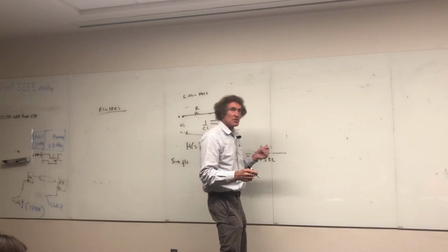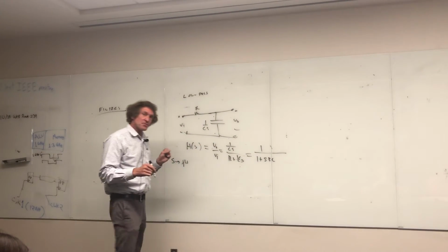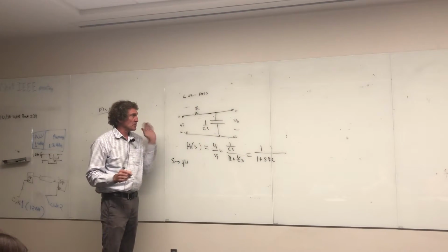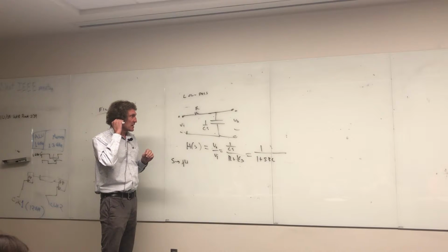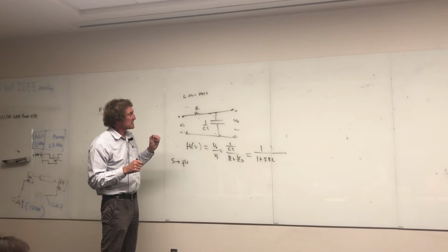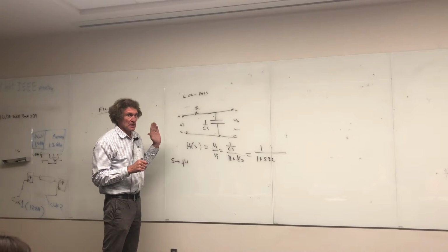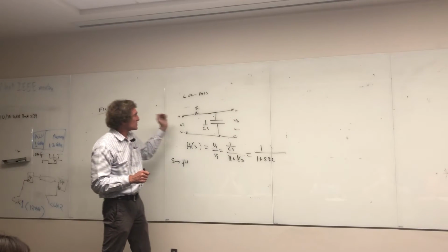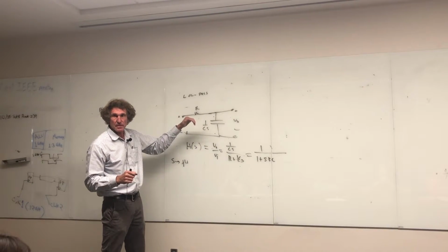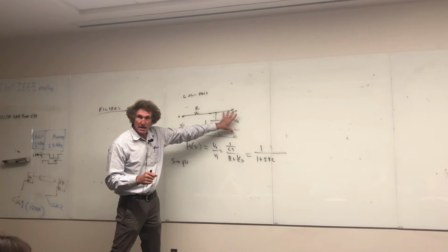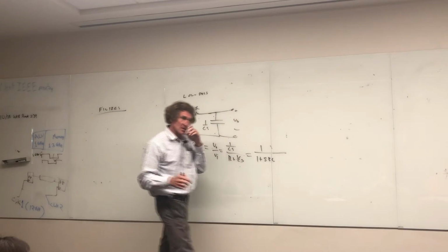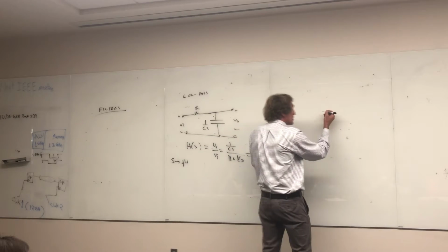Another low-pass filter you could do, I want to say one other thing. This filter, if you just put an output-input signal, it has one interesting thing, that at DC, if this is a high impedance load, virtually no current flows. Right? If this is touching a high impedance, like 2 megohms or higher, something like that.